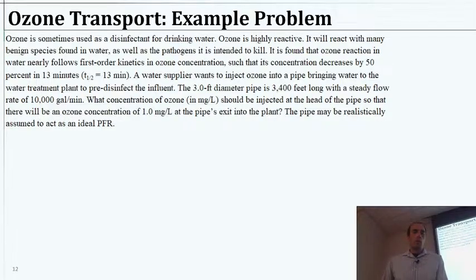All right, so ozone is sometimes used as a disinfectant for drinking water. It's highly reactive, and so on. It's found that its reaction with water follows nearly first-order kinetics in terms of ozone concentration, such that it decreases by 50% in 13 minutes. So its half-life is 13 minutes.